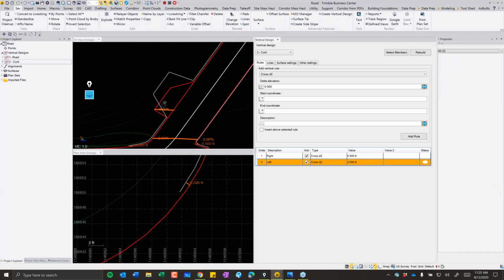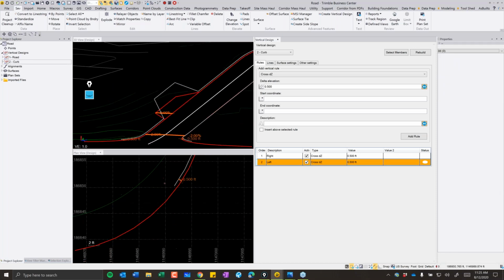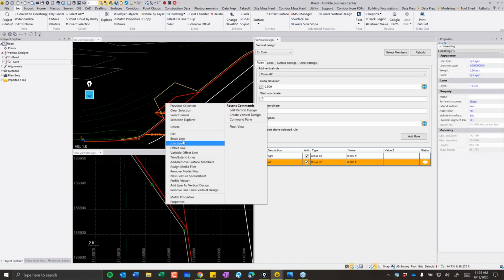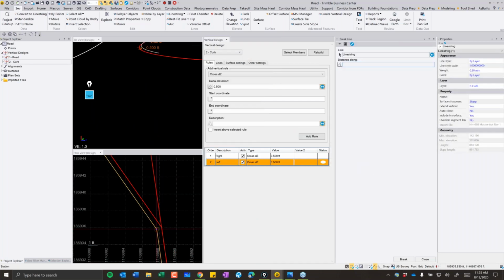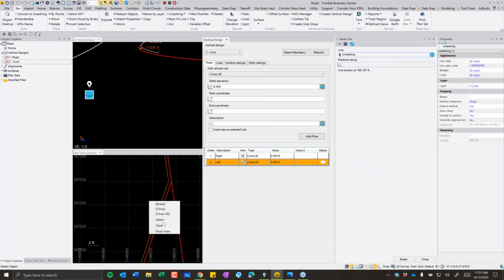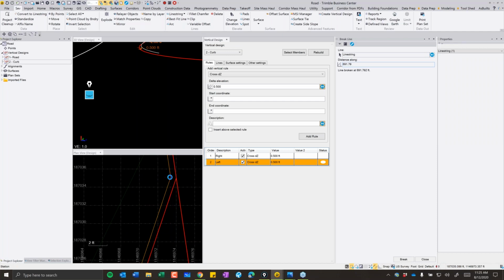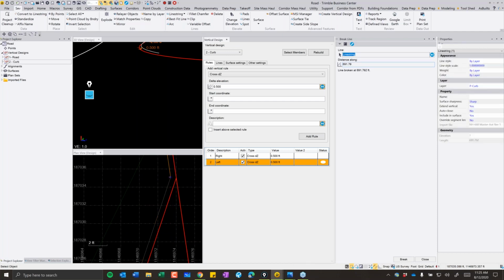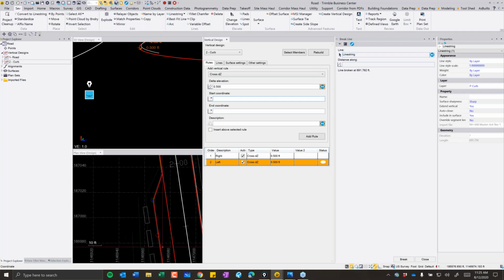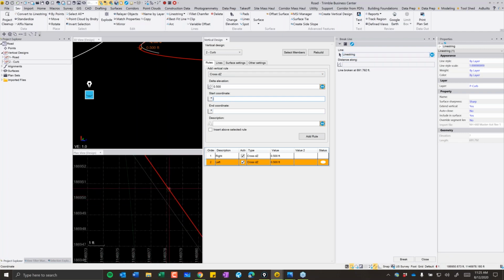Right here, you can see how this blew up because it's not correct. So we just go back in here and we break this section. Because what that's doing is it's actually doing 0.5 off of that travel way, because the lines were separated to do the main pavement. They're not one continuous line, therefore it can't do that through there in the same way, right?